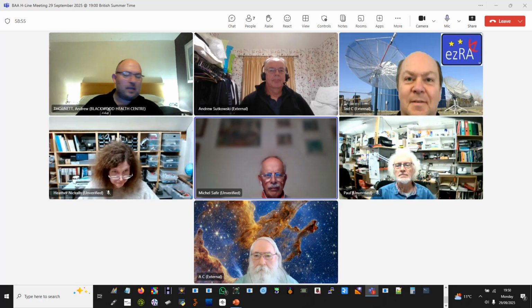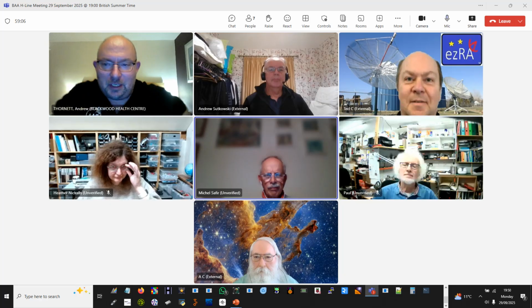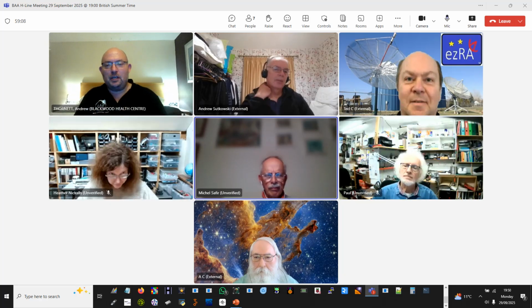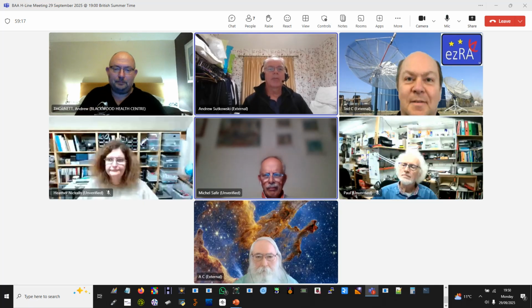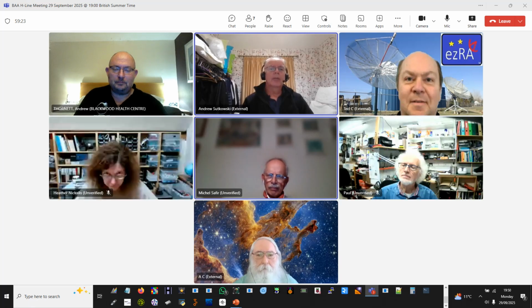I felt I was up against a brick wall and didn't know where to go. So, yeah, it's a shame because the RSP Duo seems such a wonderful piece of kit. If you can get it actually working, to have two channels which are co-clocked is a brilliant idea. Yeah, the problem with it is that on a single channel you can have 10 megahertz bandwidth, but on dual channels it's 2.5 or 2.4. So that's the unfortunate bit with it.